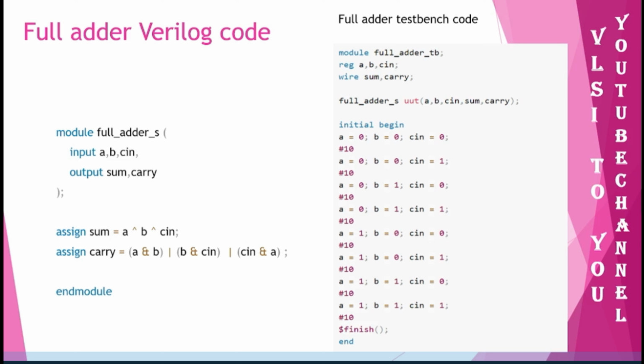You are not writing any logic within the test bench. You are going to test the logic that you have written in the RTL code with the help of this test bench code. So for any of these levels of abstraction, the test bench is going to be the same. You need to remember that, right?